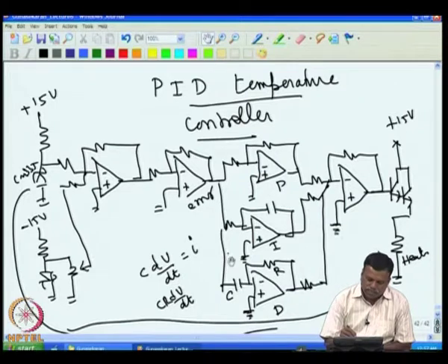But any change, whether it is noise or the error, cannot be distinguished by this capacitor. So what we do is take C smaller, so that the noise response is smaller. That is why we are selecting the lowest time constant for this.